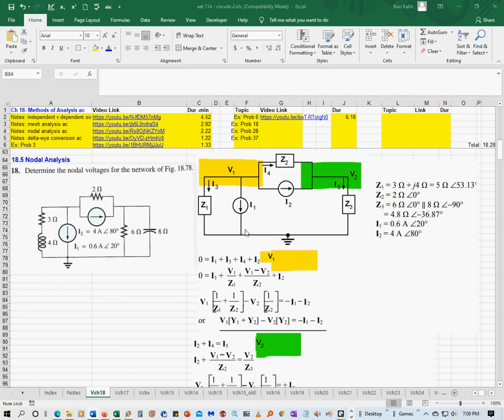So do we have any currents going into V1? Well, actually the first thing you do is label all your unknown currents as leaving the node. So they labeled I3 over here going through Z1. They didn't use I1 because I1's already taken, and I2's already taken. So they called this I3 leaving here. And the only other unknown current is going through Z2, and they called that I4, again because I2 was already taken. So now you do KCL at that node.